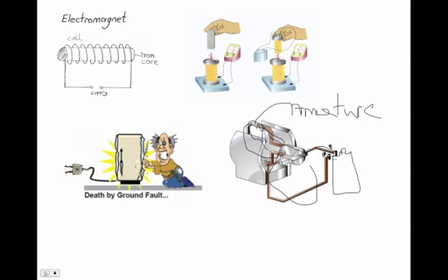Now, as it spins, this thing here helps to change or reverse the current. Right now, if the current goes in this direction, this will be north, and down here will be south, and it'll spin away. This is our permanent magnet, like a horseshoe magnet. So P for permanent magnet. So if this permanent magnet had a north end, it would spin in this direction because north and north push away, and then this would be south, and it would pull.